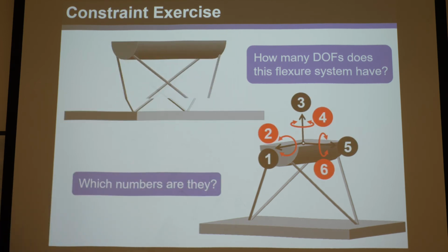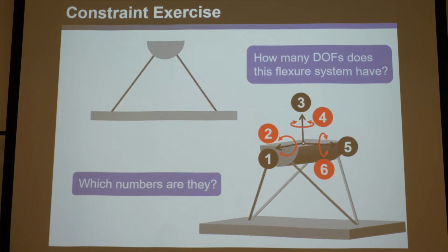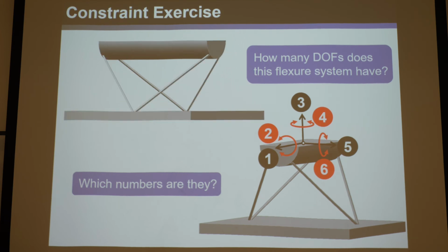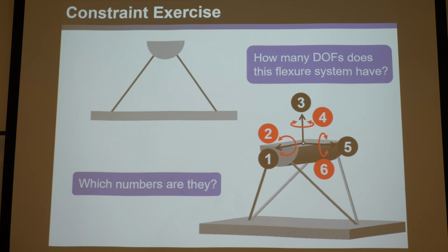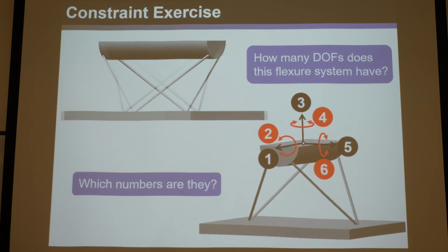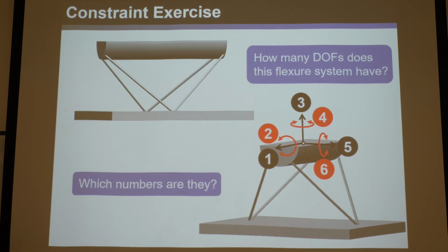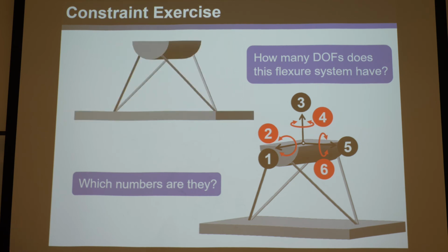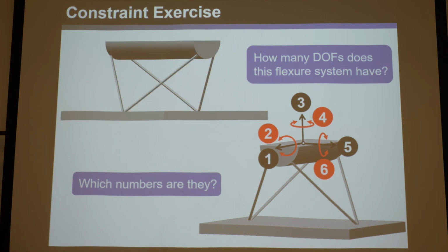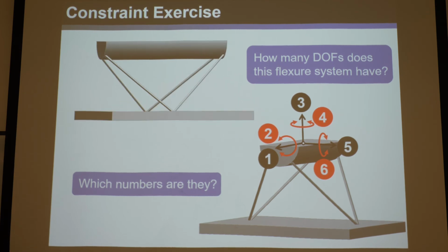So let's draw our old engineer's coordinate system with 3 orthogonal translations, 3 orthogonal rotations, and stick them there. Remember, where would we even stick them? Well, okay, we stuck it on the top. That's kind of arbitrary. But tell me which ones this kills. Which ones remain? Because we know there's got to be 2 of them.